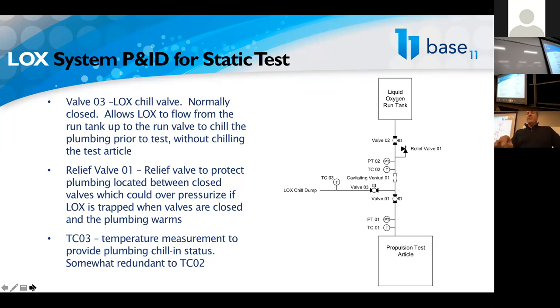So we'll put enough tubing between the connection and the location of the actual relief valve, so the relief valve doesn't get cold. And so now it's going to behave in a much more predictable, reliable fashion.